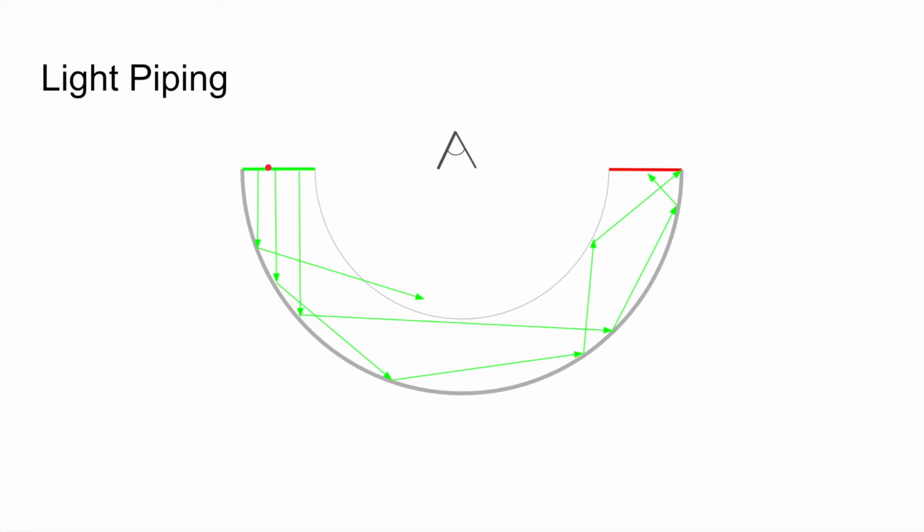Here's another situation where the light comes in, hits our sensing surface, and is reflected into some direction, and its angle is greater than the angle of TIR. So it just bounces out of the surface into the air region and goes wherever; I wouldn't know what the trajectory of that would be. And then finally, we have some nice rays that come in, hit the surface, hit the plastic-air boundary, bounce off, and then stay within the sensor until it reaches the end, where it's absorbed by a filter.